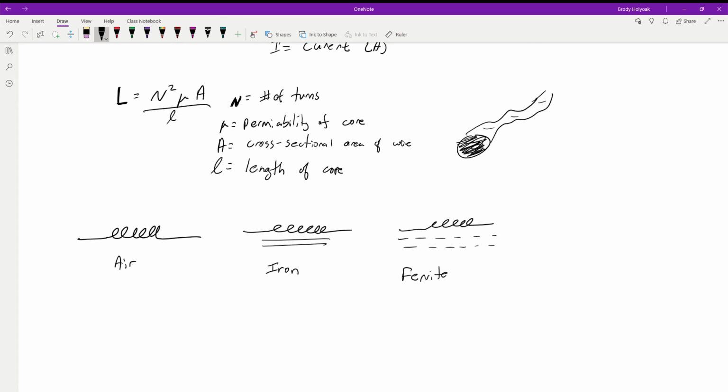You'll see these symbols on schematics, especially if they have different kinds of inductors on there. It can help you identify what you're looking for, because an air coil is just going to be like a paper or cardboard tube with a wire on it. Sometimes it's just a little package, but if it's wrapped around an iron or ferrite core, those are big and bulky, and you can usually see where they are, so if you know what you're looking for, it's a little bit easier.